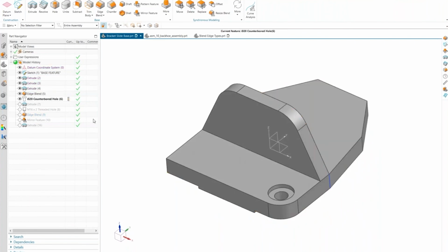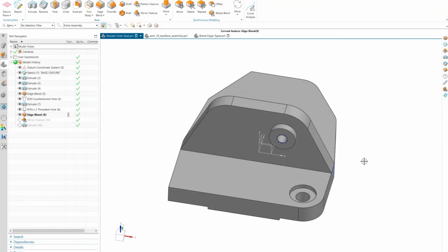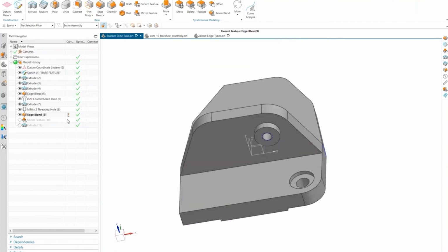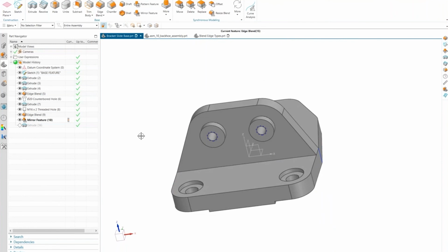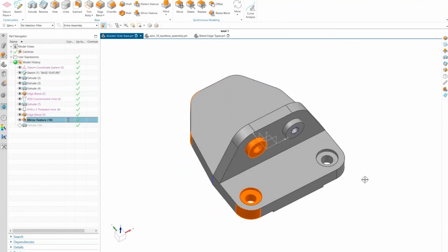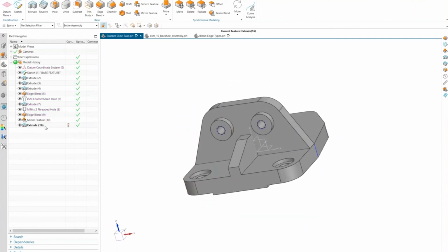And then I'm adding some additional blends, holes, bosses, more holes, more blends. But you'll notice that I'm only adding it to one side, and that is intentional, as I'm once again trying to use the symmetrical aspect of my part and a feature or a tool called mirror feature. And I can grab all those features and mirror them across the origin center there. And add in a rib.